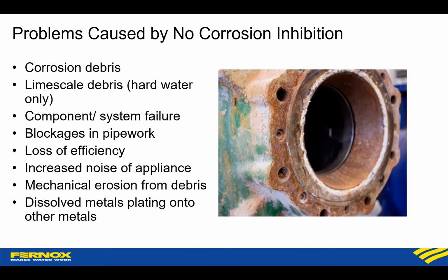I mentioned before mechanical erosion from debris. Obviously, the more sludge you have, and depending on the type of sludge, if it's metal oxides, having that going around your system at a higher flow rate is going to cause some damage to the more sensitive components.